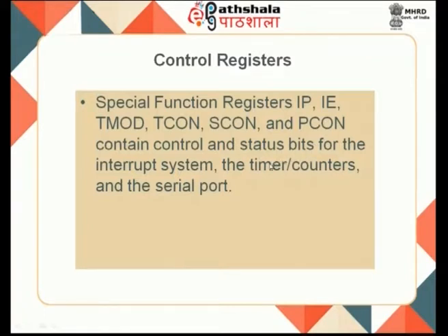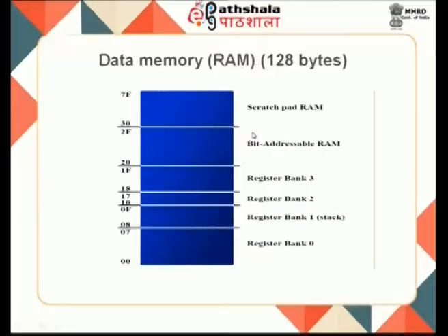When you are looking at the IE, we will be setting a particular bit which in turn allows the system to work on interrupts. In the same way, for timers and counters, some of the bits will be set or reset with your TMOD, which enables or disables these timers and counters, and the serial port communication is enabled through your SCON.